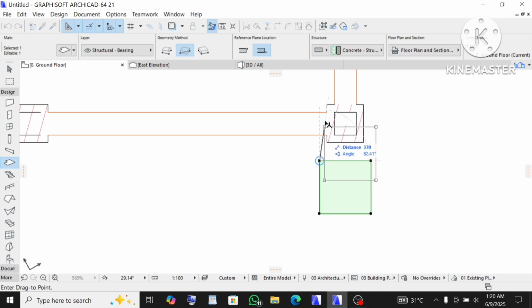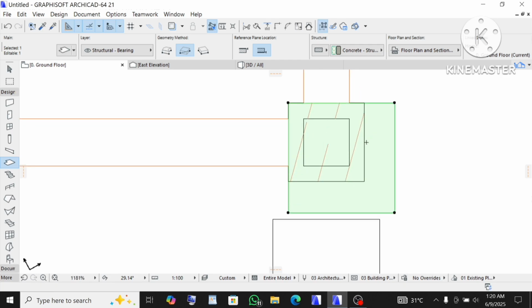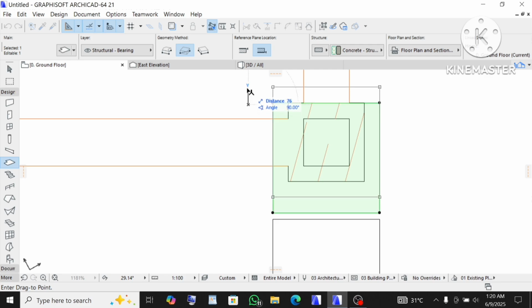take it up like so. So remember that what we added as offset was 150, which is 75 to the left and 75 to the up. So press Ctrl D on the keyboard, click, take it to the left by 75, press enter, press Ctrl D also, click, take it up by 75 and press enter, such that it will be at the middle. Alright.